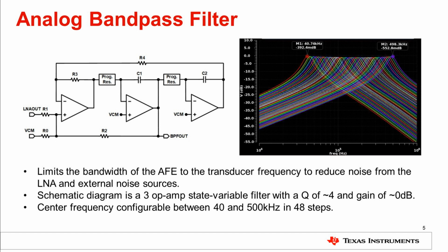In the case where the Q of the BPF is constant in a device, such as the TUSS44X0, the bandwidth increases as the center frequency increases, resulting in an increase of integrated noise. And the TUSS44X0, using the alternate high-pass filter, becomes favorable for center frequencies above 500 kHz to limit the amount of 1/f noise.